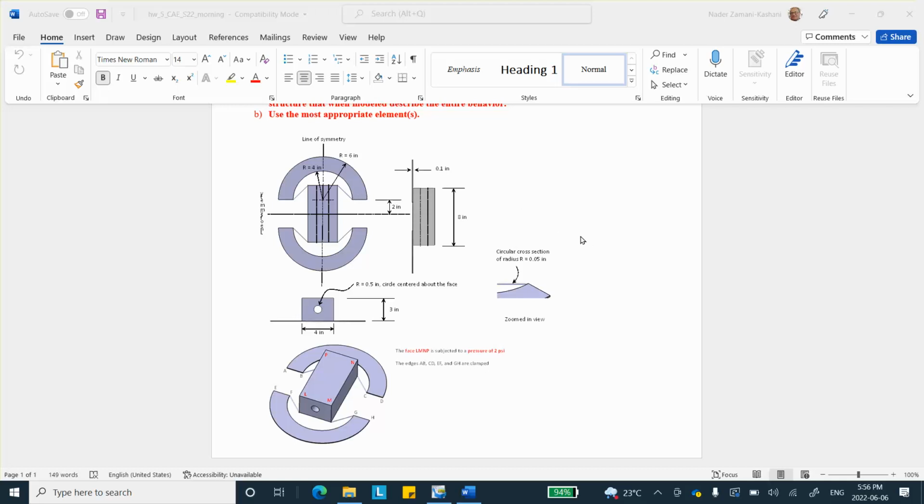Because otherwise you might say, well, where is this beam coming to? Is it coming to the middle of the C-like structure, the top of it, or the bottom of it? Because we're modeling this thing as a surface and meshed with shell elements, there is no ambiguity. Everything goes to the middle surface of the shell.